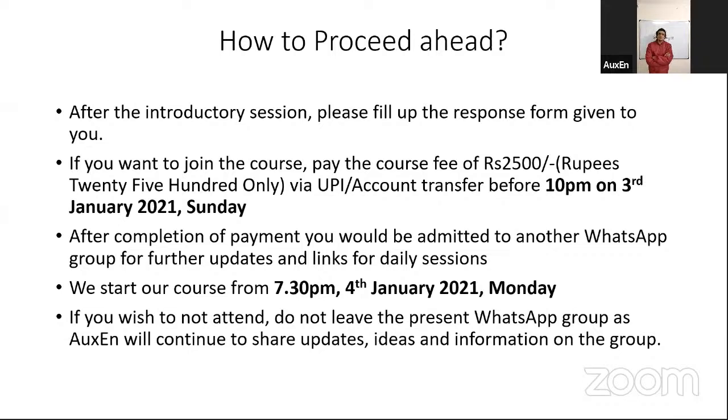For example, for vibrating type of machines, you have to calculate the frequency of your machine and the frequency of your soil and footing system, isn't it? So that's how you have to work out your size. Once you work out the size, your normal design of foundation remains more or less the same. Okay. So I will try to include some concepts related to machine foundation also because it is a useful topic to cover.